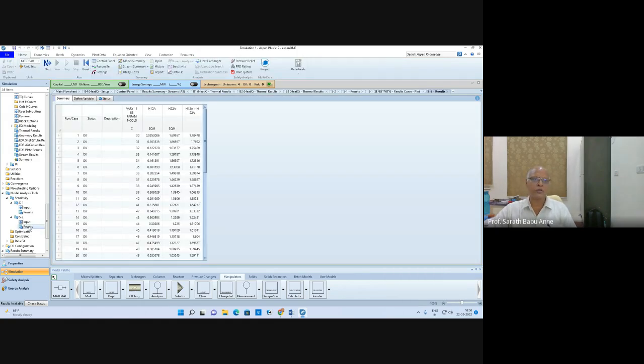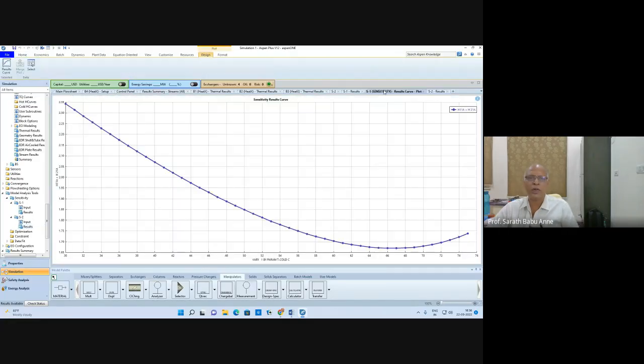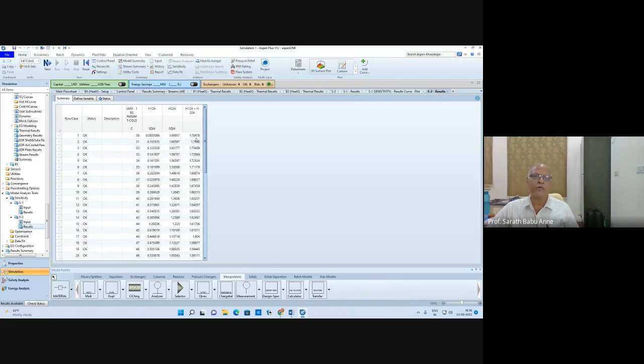And what about option 2? Again, you can see the same trend. Increasing the temperature is going to show a decreasing trend with respect to the total area. But one difference that you can observe in the case of sensitivity 1, when the outlet temperature from the first exchanger is 30, the total area was 2.35, whereas in the second case, the total area was 1.78. So this is giving the same result with a sum of areas lesser than in the first option.